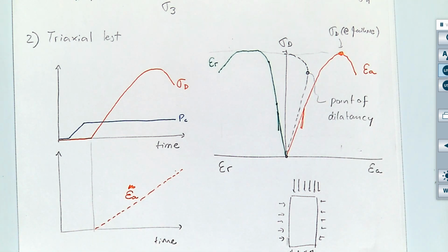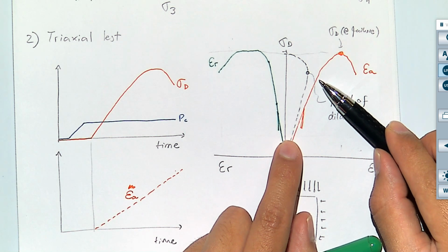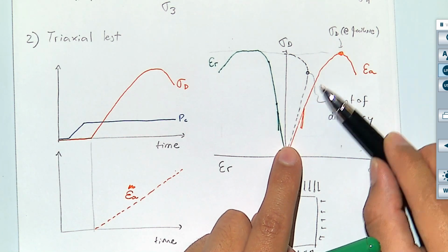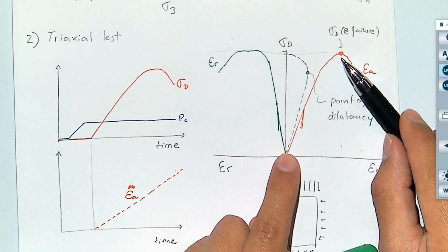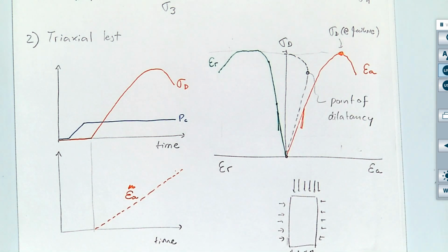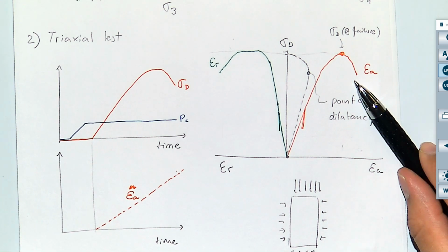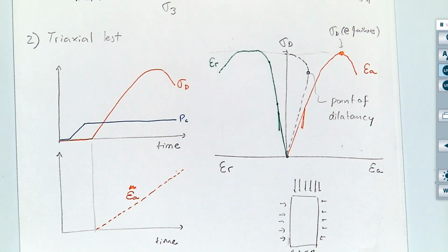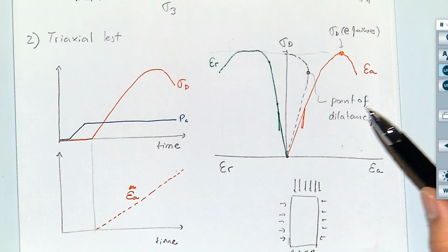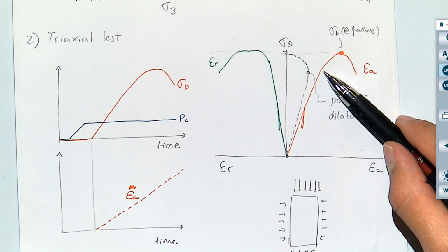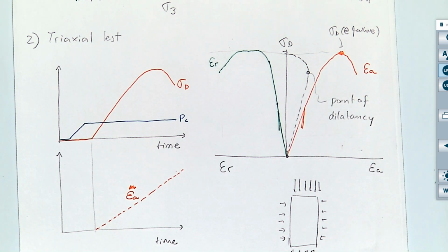That's why usually the Young modulus is measured at 50% or less of the peak stress, because if it's close to the peak stress, the rock is already broken. When you are analyzing some target formation and you send this test to the laboratory and you get the results back, you should check the stress strain curves and make sure that they actually report Young moduli which are not close to failure, because otherwise those Young moduli are going to be quite different to the ones that you actually need.